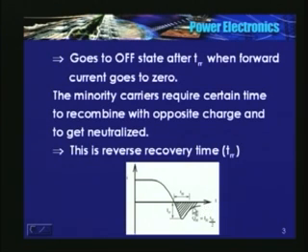And this is the charge, the reverse recovery charge. Now, what is the reverse recovery charge? It is the area of this plot. I am assuming that this is linear, so I am just determining the area of the triangle to find the reverse recovery charge.